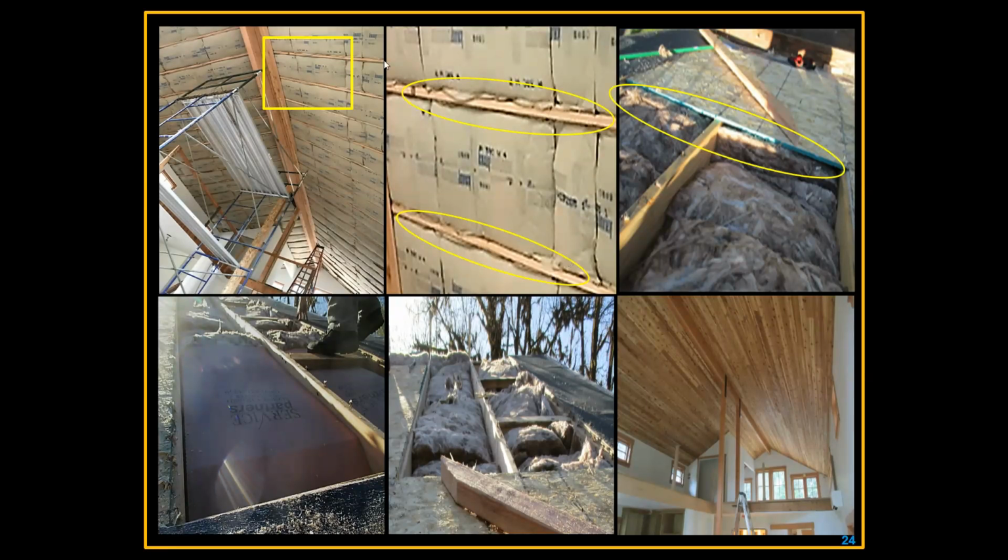So what happened is they did a couple of things. They improperly stapled. Even the side stapling is not properly stapled. They used really small pieces to fill in things instead of using full batts. So they got more gaps than they may have in the first place if they had used longer batt material and saved their scraps for other things rather than filling in a full cavity with them.